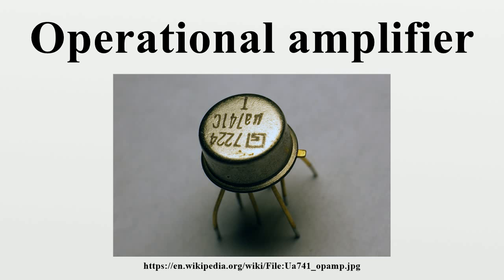In the non-inverting amplifier on the right, the presence of negative feedback via the voltage divider R_F, R_G determines the closed-loop gain A_CL equals V_out over V_in. Equilibrium will be established when V_out is just sufficient to reach around and pull the inverting input to the same voltage as V_in. The voltage gain of the entire circuit is thus 1 plus R_F over R_G.